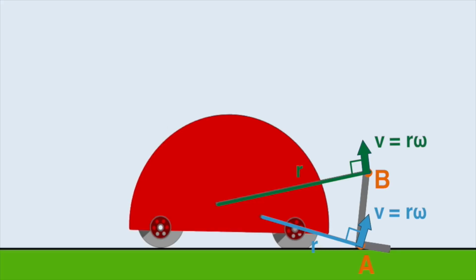Now, if you have a body that's moving in complex motion, the radius of curvature is not constant, nor is the location of that pivot point. As it turns out, it can be shown that for any rigid body moving in planar motion, even if the motion is complex, there will be a point about which that object is rotating at a given instant.